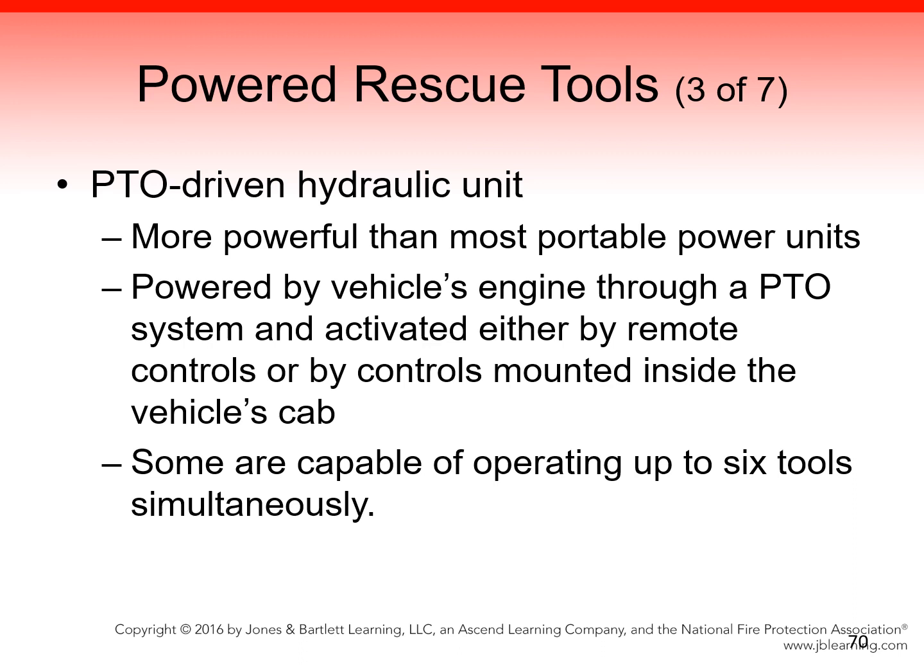PTO-driven hydraulic unit. More powerful than most portable power units, powered by the vehicle's engine through a PTO system and activated either by remote controls or by controls mounted inside the vehicle's cab. The apparatus engine usually must sustain a set RPM to achieve the hydraulic pump's required RPM. In most cases, the engine must operate in high idle position to meet this demand.